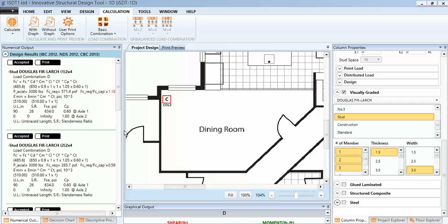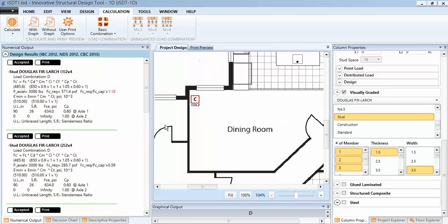So in that case, of course, we see 4 by 4 members, and then dead load and dead plus live here. And then you see this one 2 by 4 members still not adequate right now. So in that case, we may increase the size here, so that we can do as you need it, like this way.